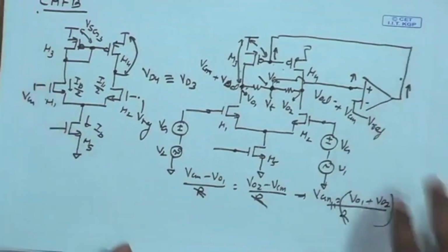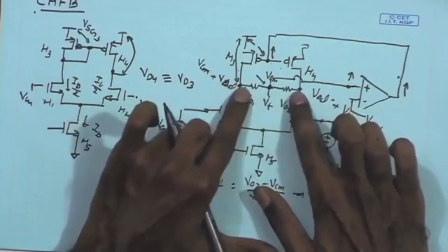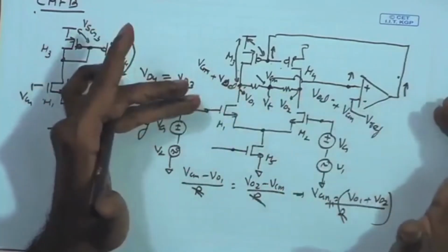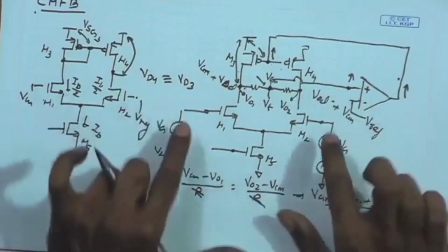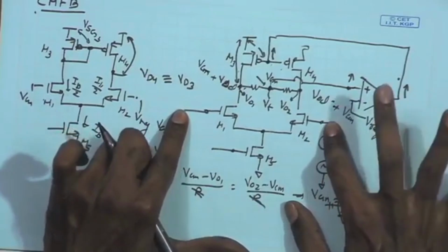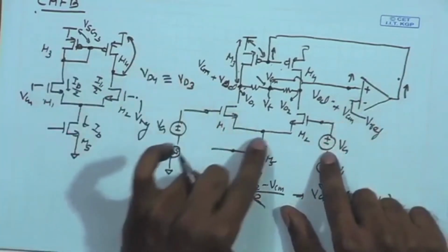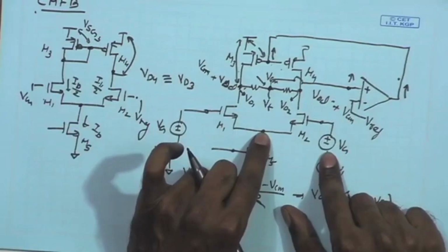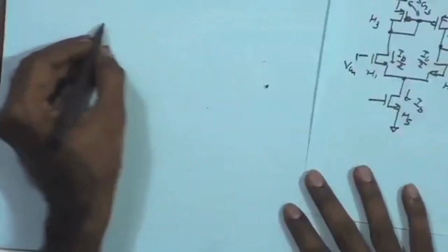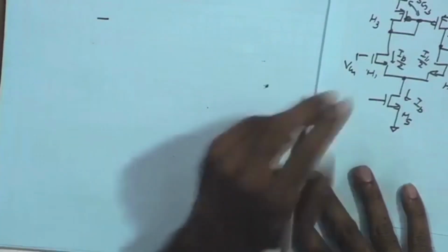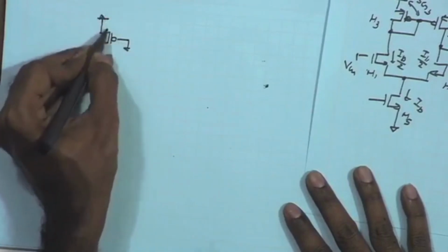Now, of course, what is the effect of this resistive voltage divider on the differential operation, that also needs to be considered. If I look at the differential operation, once again if I assume that the DC bias point at the gate are same, well defined, in the differential half circuit this point will be AC ground, and as a result I am going to draw the differential half circuit with the PMOS gates at AC ground.